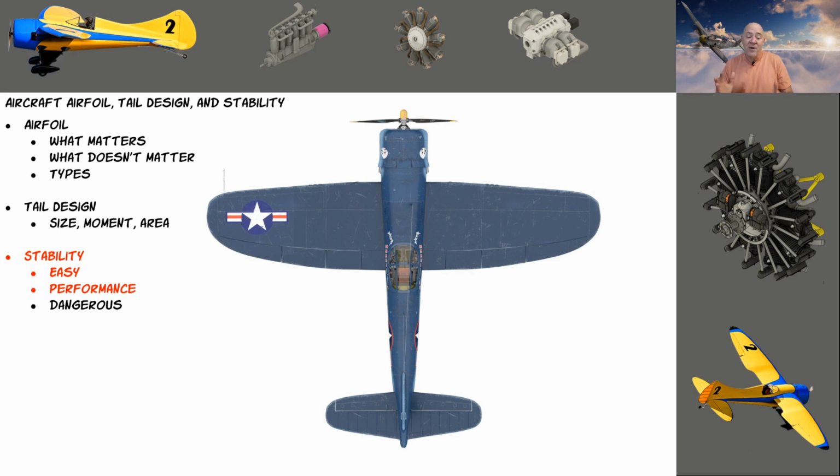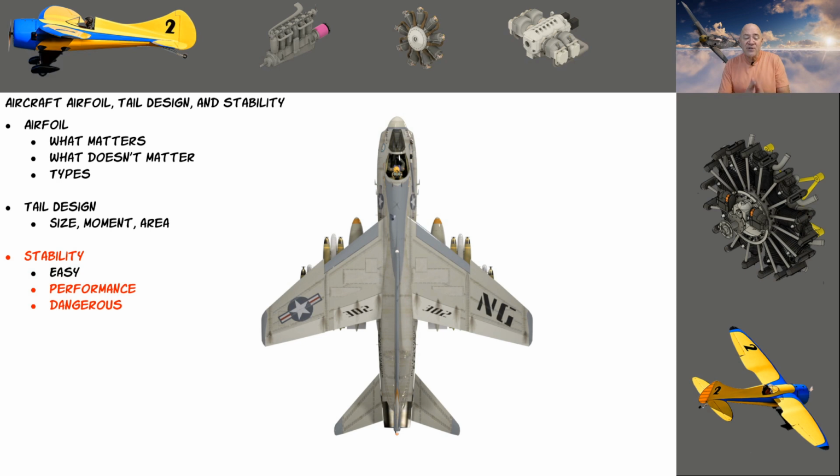Corsairs have a long tail, a lot of square inches in the horizontal. I still call this a performance aircraft. But this is where you've got to start thinking about how big your horizontal stabilizer is and what type of stabilizer it is. A stabilator means the entire stabilizer is moving. And I have helped at least 10 people get their EDFs or their planes, and I'm not talking about an ARF, trimmed out. If you look, most stabilizers only go up about 25 degrees and down 15 degrees.